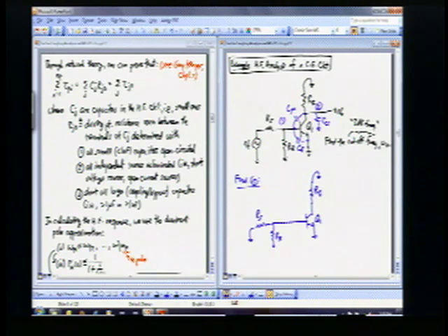Whoops, I'm trying to do tau 1 right here. And C-pi is the only capacitance I see in shunt with tau 1. Okay, well actually I do open circuit them all. So I open circuit all of these small capacitors. But then at this point where C-pi used to be, or at my node 1, I'm going to put a voltage source here, Vx, and measure that Ix there.